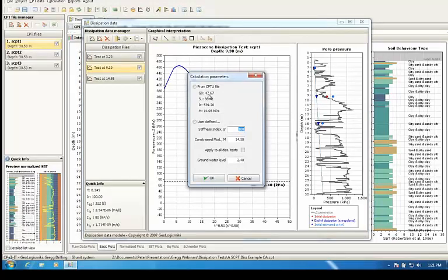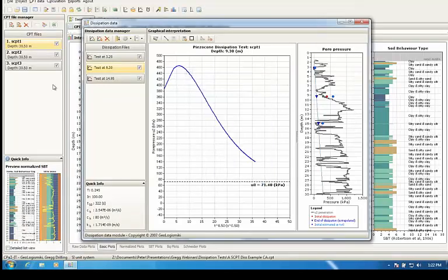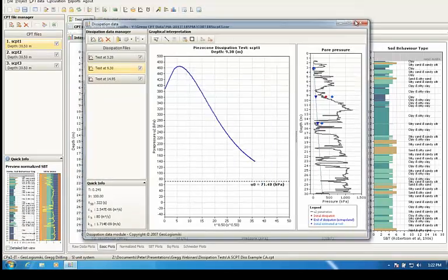There are a variety of tests you can do. With CPT equipment, you can push in groundwater sampling devices, which are essentially a bit like standpipe piezometers, and you can do slug tests, where you can do falling head or rising head permeability tests with devices that were pushed in with CPT equipment. So there are a variety of backup tests.